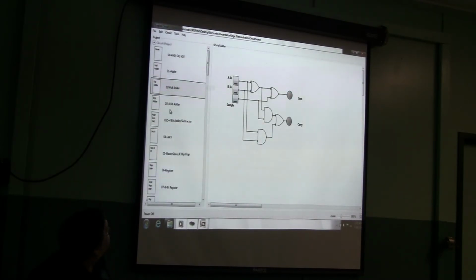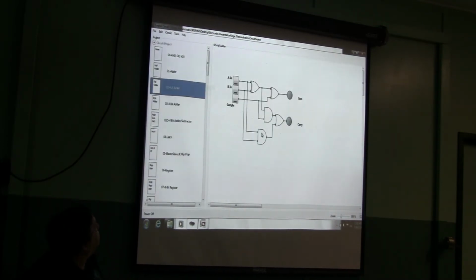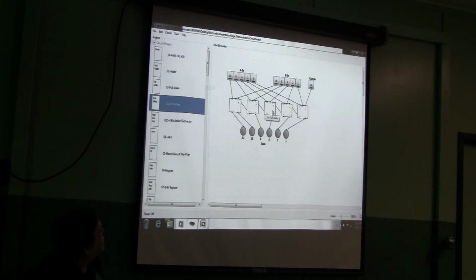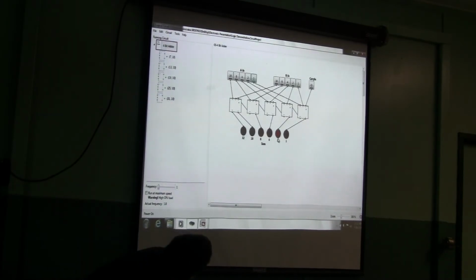And now I'm going to take those, I want to add more than just 2. So everything on this screen is now inside one of these boxes. So if I want to add 1 plus 1, then it's 2. The output's 2. So the 1 and the 1 both go to this first stage. The output of this first stage would be a 0. It carries over to the second stage. The second stage says, okay, all I have is a carry. I don't have any other inputs, so my output is on. It is on. Yep. Okay.